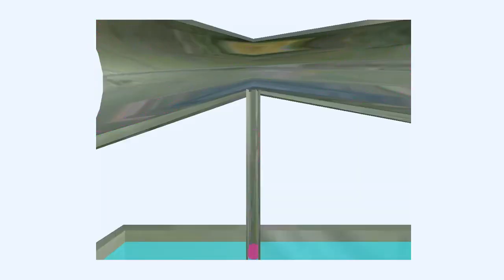A suction applied to a tube immersed in a liquid is sufficient to raise a column of liquid to a certain height up the tube. Should a small hole be made in the tube, under the same conditions bubbles of air will enter the tube and the liquid will be drawn up the tube in smaller drops rather than a continuous stream. In other words, the liquid will be diffused or made to intermingle with the air. Air bleeds into the tube and reduces the forces acting on the fuel, reducing the flow of liquid through the tube.